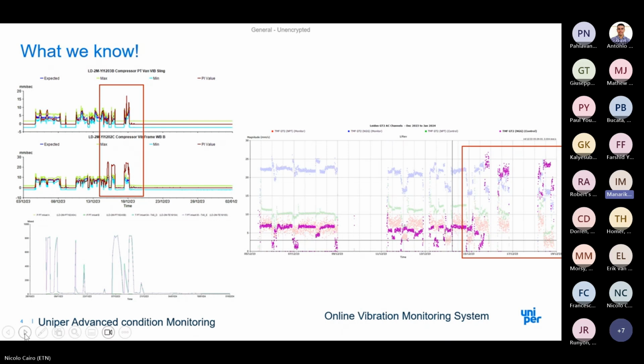And on the bottom left, you can see the combustion analytics, where we haven't spotted anything, which is very obvious because when you have a blade loss or loss of mass, you don't expect to see a big change or anomalies in combustion because it's more thermal than mechanical. However, blade loss events or loss of mass sometimes could give spikes in combustion because it disturbs the flow in the combustion, isn't it?